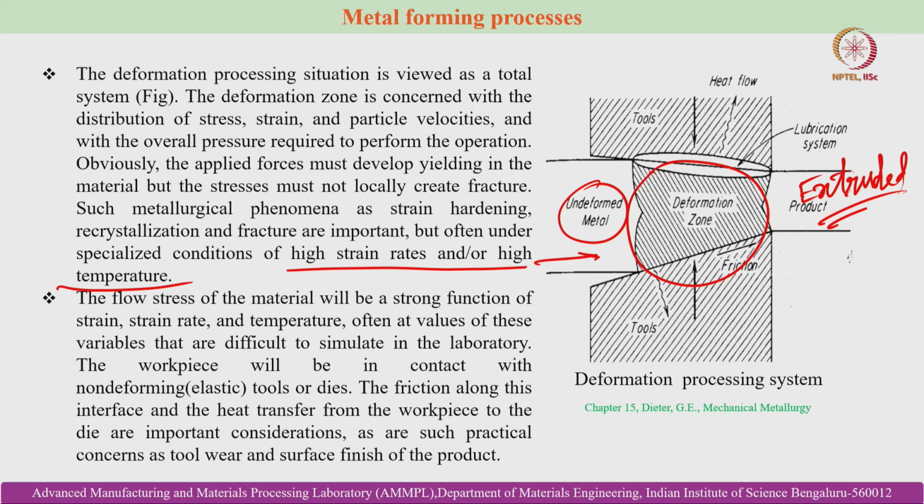So, the workpiece will be in contact with non-deforming elastic tools or dies, and the friction along this interface and the heat transfer from the workpiece to the die are important considerations, as are such practical concerns as tool wear and surface finish of the product.